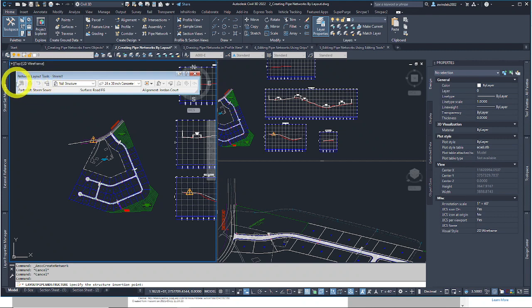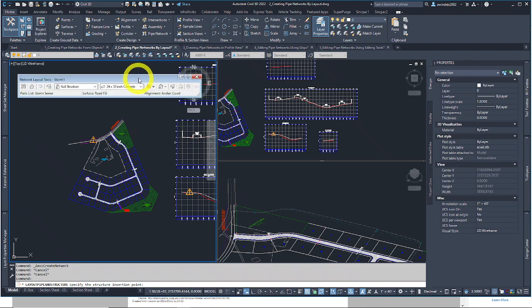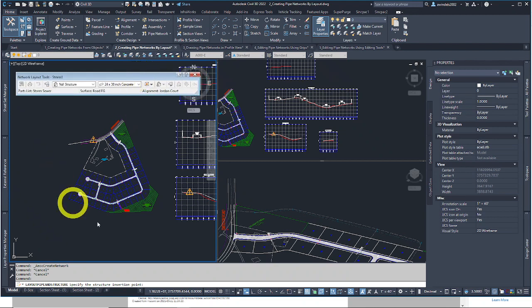So these are the 4 main things: which network, which surfaces it's getting designed in accordance to, which alignment is it associated with, which parts list is it occupying, and which parts inside do you want to add, and then which parts and pipes. These are the insertion tools. So let's start with getting into this. This is essentially the second way to make gravity or pressure pipe networks, is 1 step at a time through Civil 3D, not from an object.